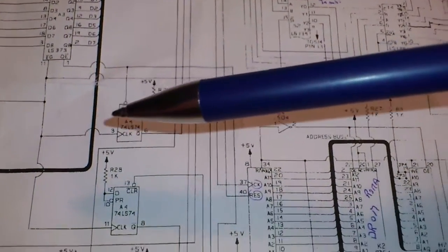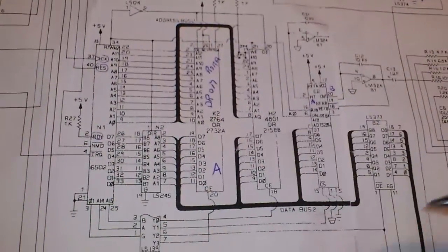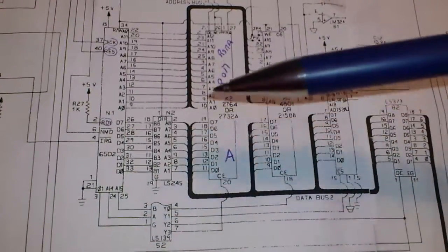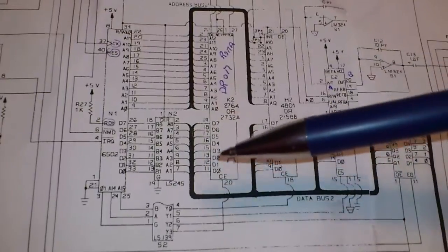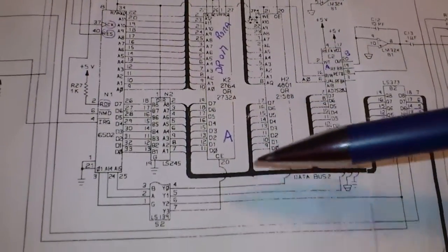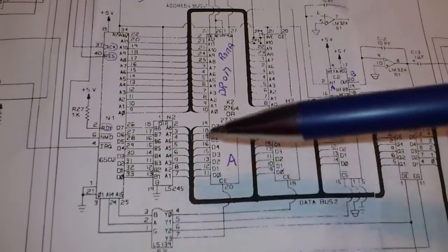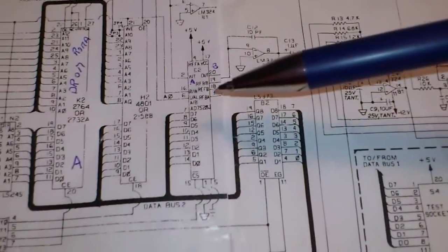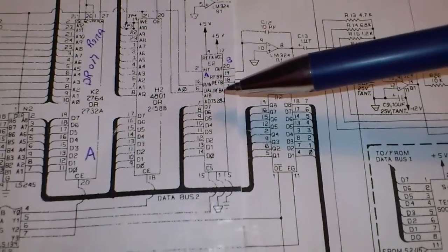If we now take a look at the easy CPU, the lower one here, we figure out that the Rockwell 6502 comes with 8 kilobytes of ROM, which is where the code is sitting for the CPU, and also 1 kilobyte of RAM, that one here. There is just an address decoder here, which, depending on the address space, selects those components. Also, it has here a 2-channel analog to digital converter, the Analog Devices 7528J.